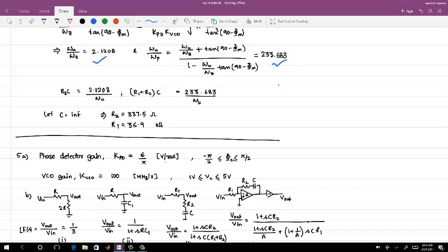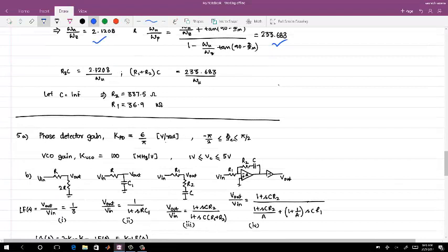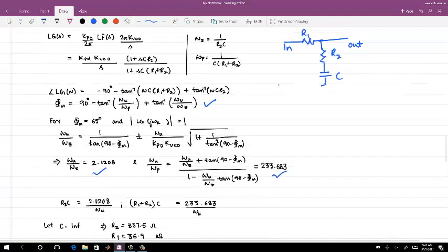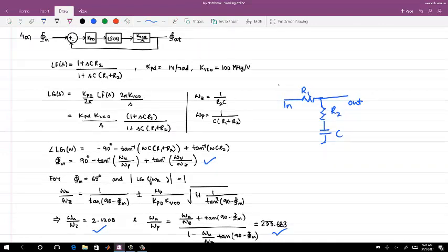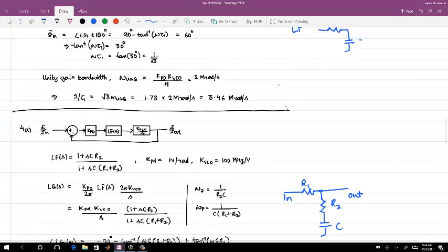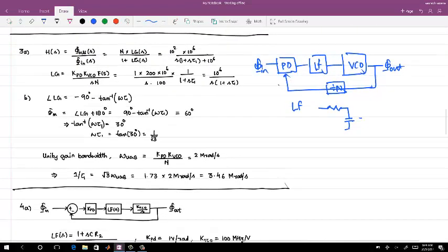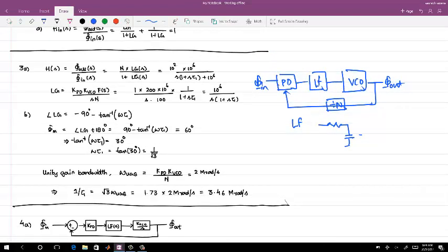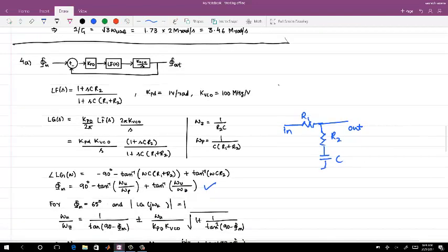It's a passive loop filter itself. So you are using only, so the DC gain is, you have a zero here, right? Initially you had only one single RC filter, right? If you have only a simple RC filter, you have one integrator, and the phase margin depends on how your RC filter is set up. The other option is you introduce another zero in the system, so you are more relaxed on the bandwidth and the phase margin part.